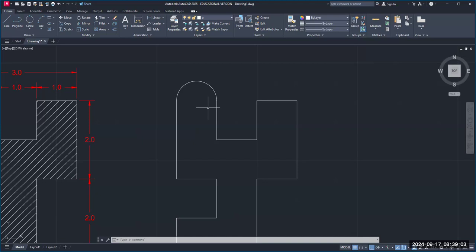All right. Now, I want to put a circle in the center of this arc here. Go to circle, go to center diameter. One more time, go to circle and select center diameter. When you move your cursor, what happens? It tells you where the center is at. Look, you just got to move your cursor over near the arc. Once you see your center, click on it, and we're going to drag out a circle that's 0.5 inches in diameter. Enter. Okay, you hit escape a couple times to get out of that mode. Were you successful in creating that circle? I see some thumbs going up. Okay.